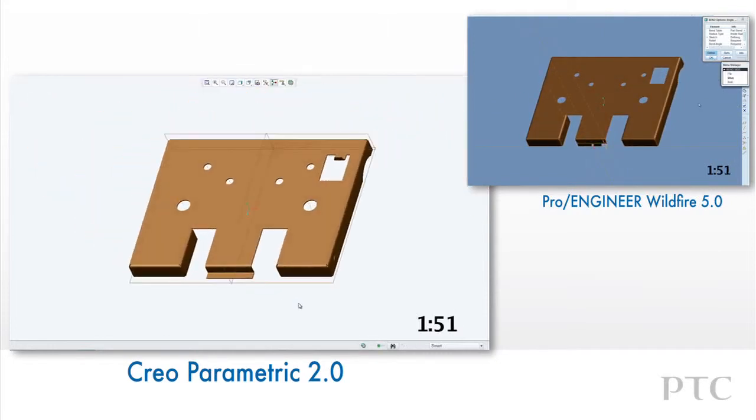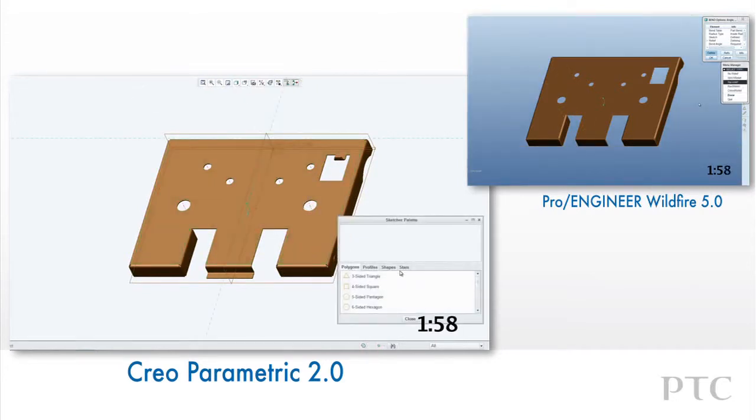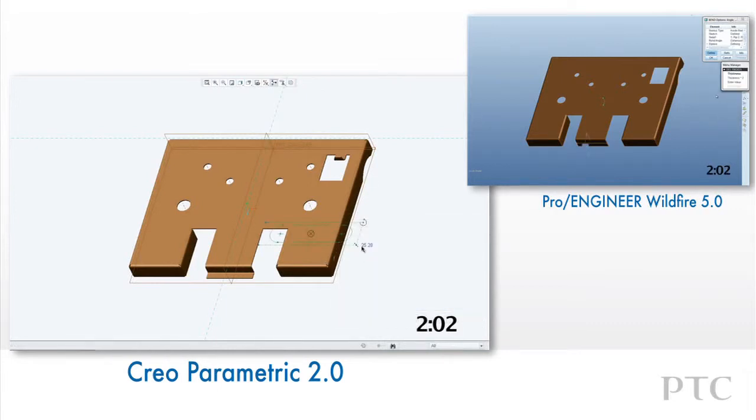Lastly, we can sketch another form by adding a racetrack section and then dragging the depth to the desired value. We can add taper and then ensure that we add rounds in the form and the intersection of the form and the walls.